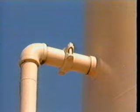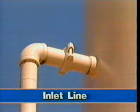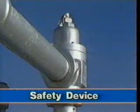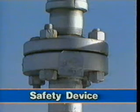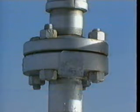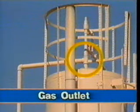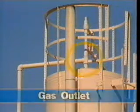Emulsions enter the heater treater through the inlet line, which is located inside the heat exchanger. The heat exchanger heats the incoming emulsion and cools the outgoing treated oil. The safety device may be a relief valve, rupture disc, or even both. They're designed to open if too much pressure builds up inside the treater. Gas exits the heater treater through the gas outlet and then into the gas line.